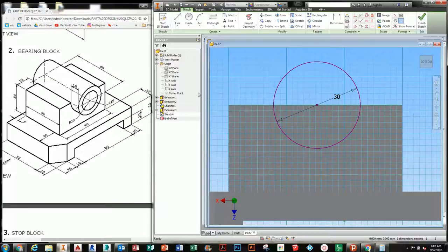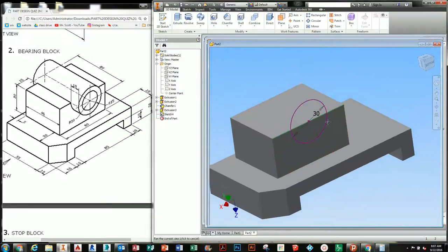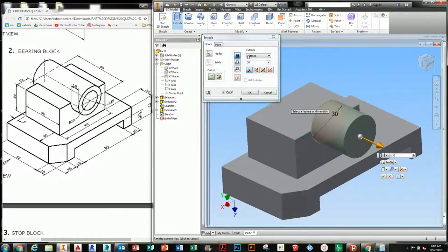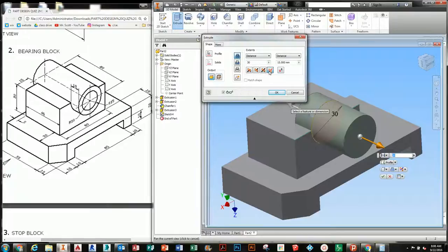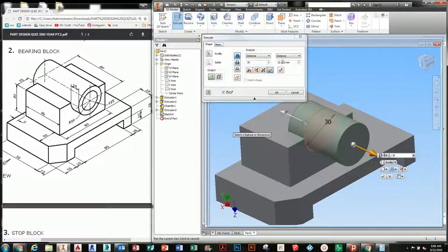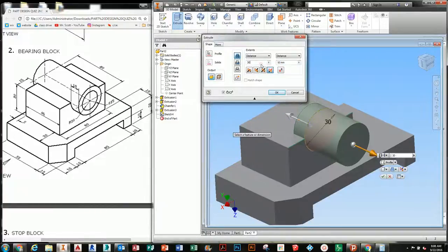And then the first thing we're going to do is finish that sketch. Because here's where it gets tricky. We're going to extrude this sketch, but this is not a normal extrusion. We have to, instead of do a symmetric or one direction or the other, we have to do an asymmetric extrusion. So the yellow number is our first one, and the silver one is our second number. Now, we got to do a little bit of math. The silver one right here is 10, so I can go ahead and make the smaller one 10. Oh, or rather, the yellow one 10. See how it shrinks to this size.